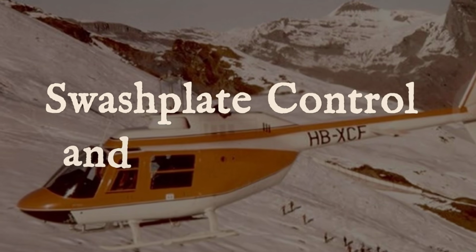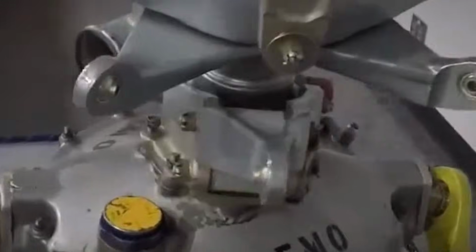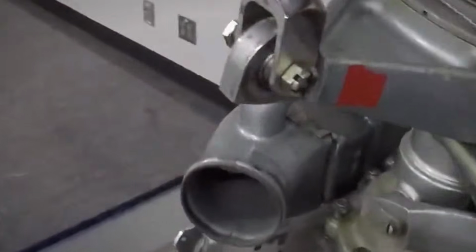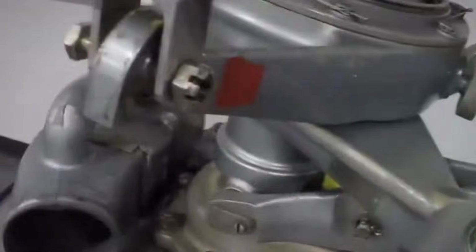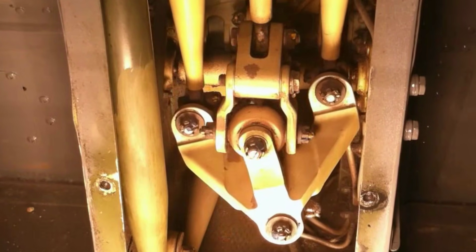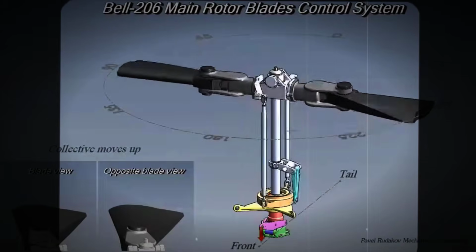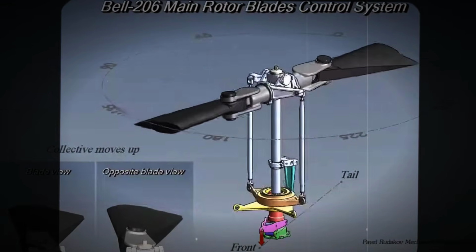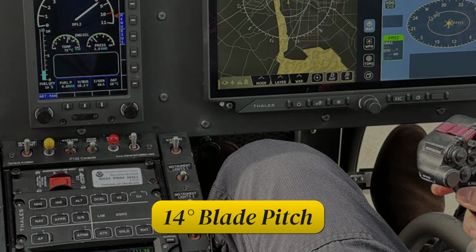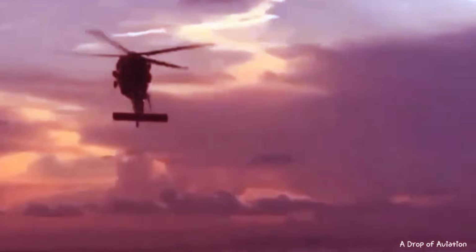Commands from the cockpit pass through a single spinning hub, the swash plate. Hidden beneath the rotor, it translates every pilot input into precise blade movement. Raise the collective lever, and the stationary plate lifts, increasing all blade angles together. In most light helicopters, blade pitch shifts from 0 to 14 degrees. That narrow range separates a gentle descent from a vertical climb.